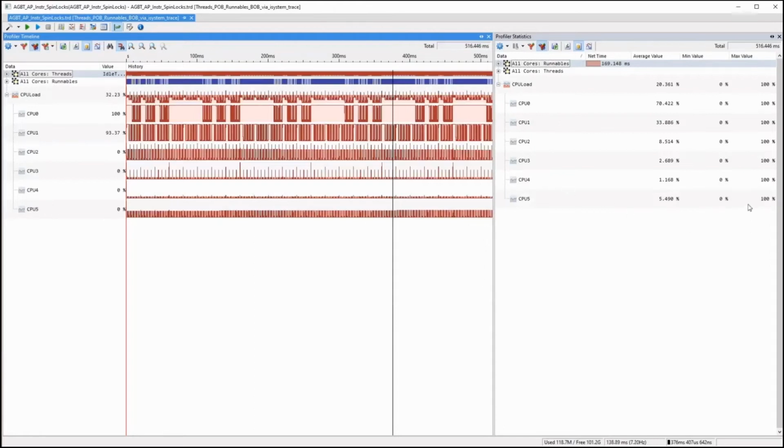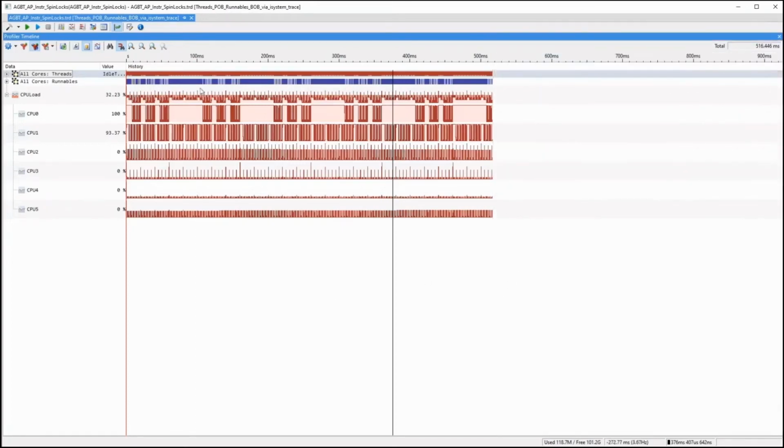Yep, okay, so we can see the average is still the same, but the min values have all gone to 0, which means that we've basically taken samples of just the idle time, and so it's going to come up as 0% executed. And then we've also taken samples of just execution time, so those will be the min and the max times that are going to be reported. So the time slice, or the period, is too low to get any useful min and max values, but what is useful is the graphic that you see.